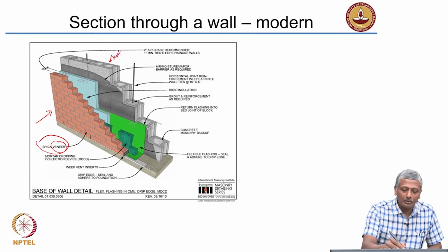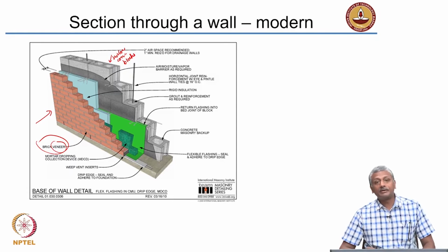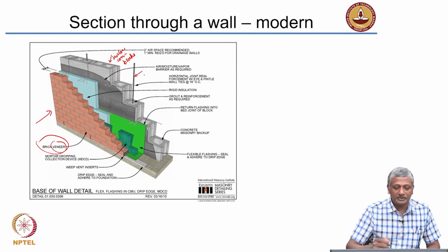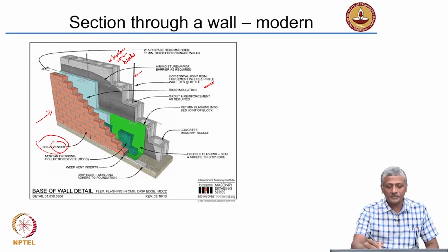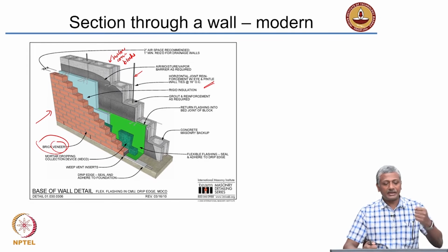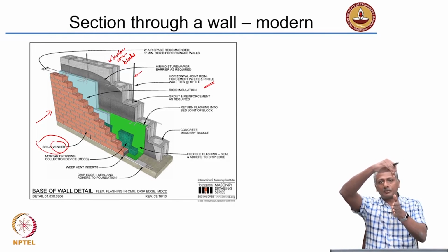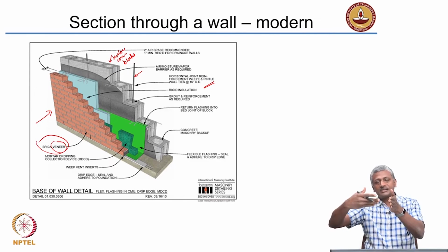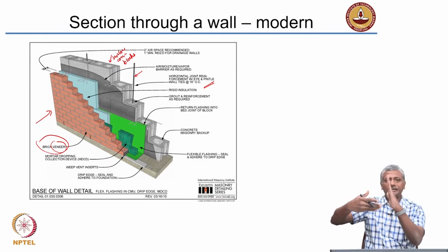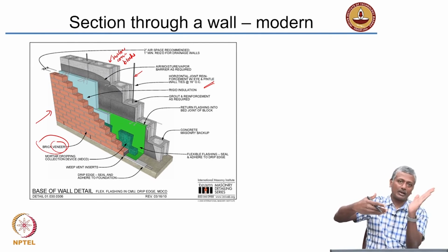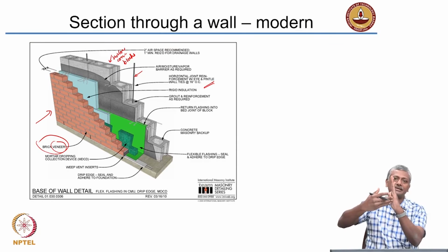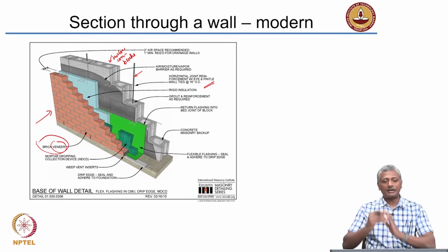These are hollow concrete blocks. Okay. Now interestingly, the hollow concrete blocks are also filled up with reinforcement. So joint reinforcement is present in every 4 cavities that is there. So what does the reinforcement do? I told you that the walls are designed to take axial load. That means the loads that come in the plane of the wall. Now what if the loads are coming along this direction? The wall has to bend like this, right? And if it does not have reinforcement, it will simply collapse. So the wall lateral resistance is increased or enhanced by the presence of reinforcement so that it can respond to the lateral loads also nicely.